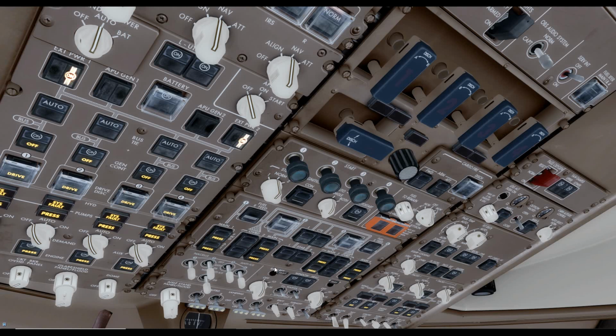We don't have pressure lights or any other lights showing in the override pump switches or the switches for the centre or stabiliser tanks. If the APU is running, you'll notice that the main 2 and 3 aft pumps will not show the amber pressure light. These will be running automatically to provide fuel pressure for the APU.